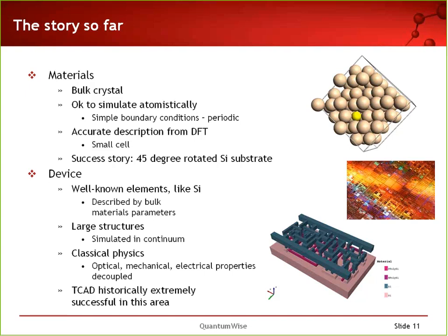And modeling, of course, has been used in the design of materials and even devices for a very, very long time. So if we look at the traditional way that modeling is applied in the so-called TCAD market, then you separate it into two areas. You either simulate the materials or the devices, but not really as a combination. Now, how does that work? Well, if you're looking at the materials, it's basically all silicon, first of all. So that makes it simple. You can use any material you want as long as it's silicon.